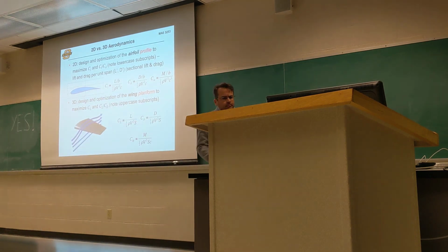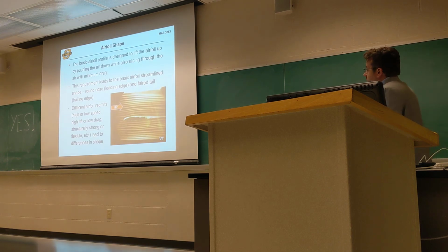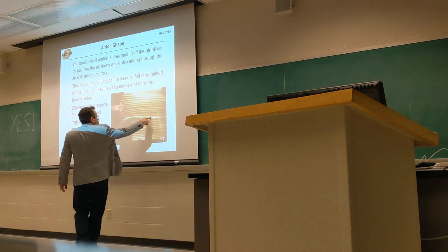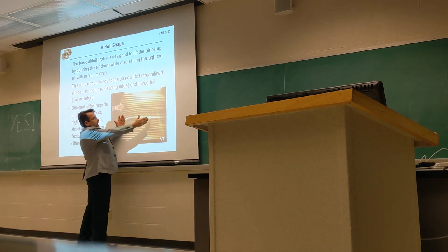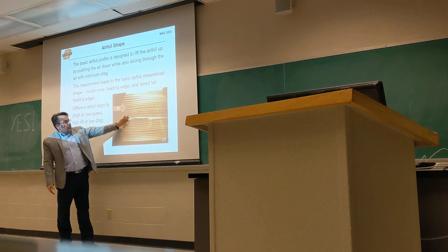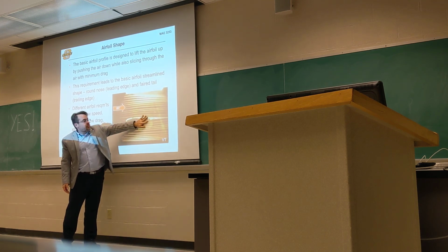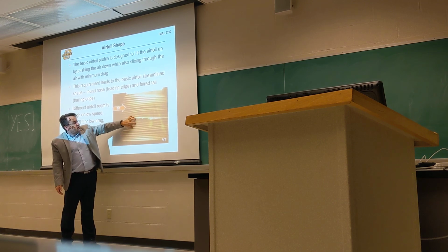Right? So this then brings us, once we have these basic parameters, to start thinking about the overall design and shape of the airfoil. What we do know is airfoils all kind of have similar characteristics in terms of, hey, I'm curvy up here, I'm sharp back here, I kind of have this flat area. Those are all there for a reason. This is primarily to provide your overall surface length for your lift. However, you may think about this as, well, S, right? I need a really big S for my lift. Well, most of your lift is actually happening right up here, okay? Because that's where the pressure is acting.